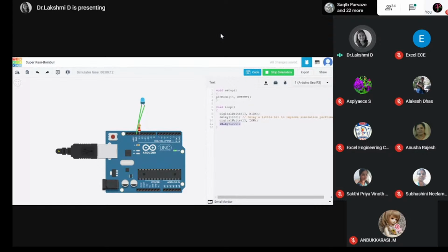This delay you can set to 500 also, then the rapid fast movement will happen. So try whatever. This resistor I'm giving to pin 12, and it is working for me, although the specifications say the pins are different. I tried for fun. 13 to 0 is working, so you can change to 12 also. This pin must be in the ground. Here you can give the resistor, and the pin you can change. The moment you change to pin 12, you need to change the code: pinMode 12, then activate with digitalWrite 12 high, then 12 low. That is the only change. Otherwise, just start imitating as such.